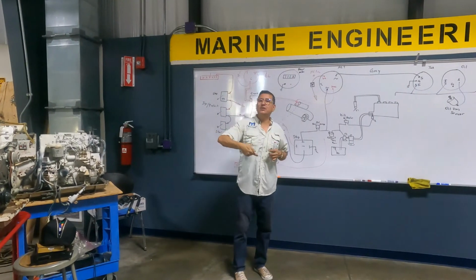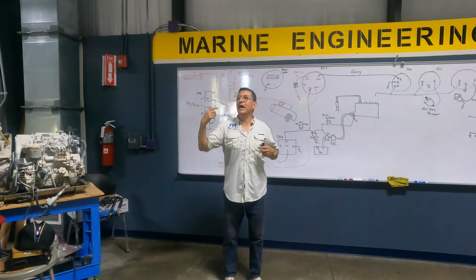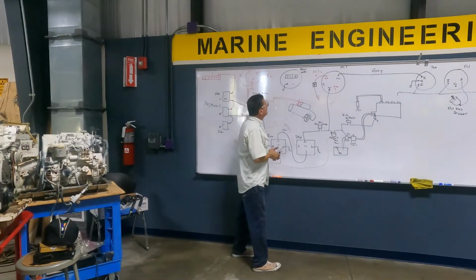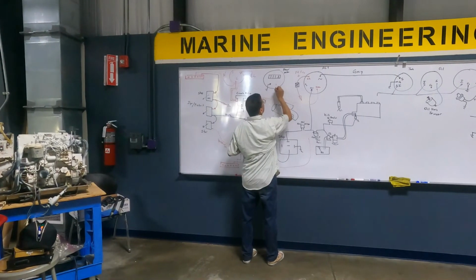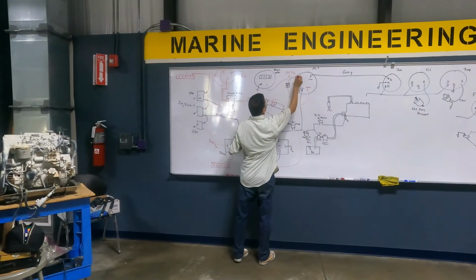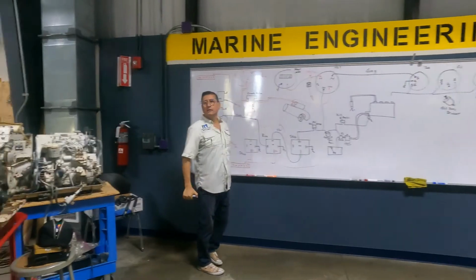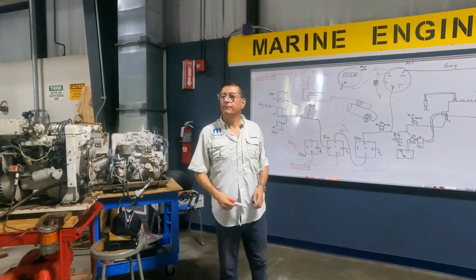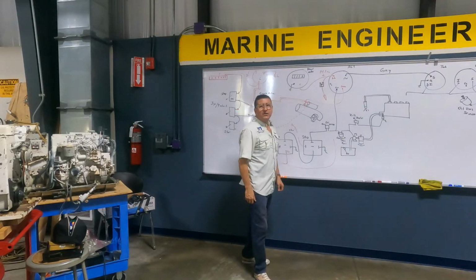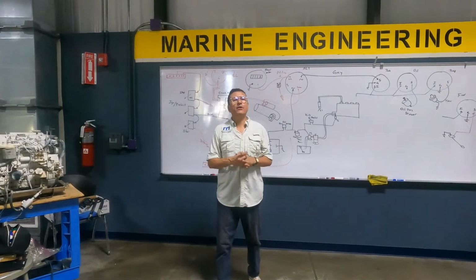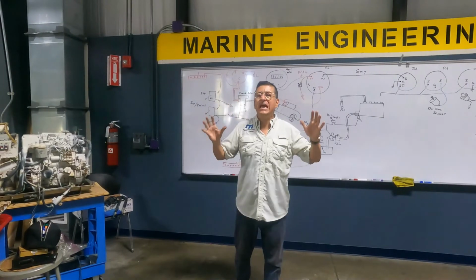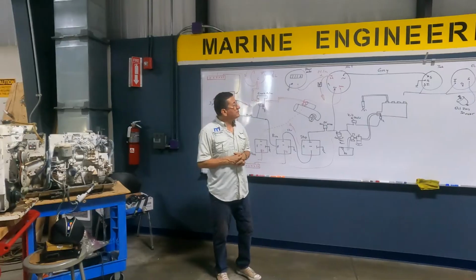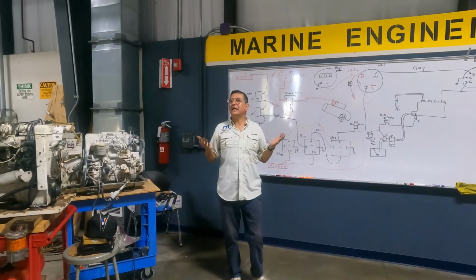Only when the alternator is producing power, the hours advance. Orange cable normally. And now, guys, you have a complete harness for any type of marine engine, gas or diesel. In this particular case, for a generator, but it's exactly the same.